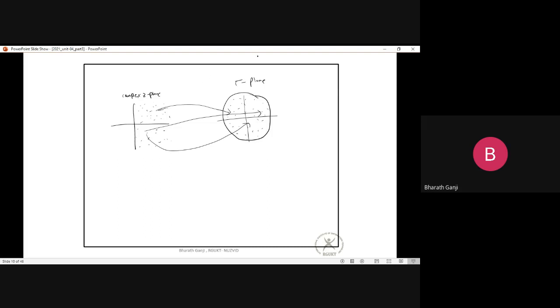And we saw that on the transmission line, if you are dealing with lossless lines, of course, we will be dealing with lossless lines only. For the lossless lines, we have one interesting property that whatever magnitude of reflection coefficient you have at the load, the same magnitude of reflection coefficient will be there at every point on the line. So the magnitude of reflection coefficient at any point on the line is simply decided by the load. Nothing else is going to change it. What changes is only the phase.